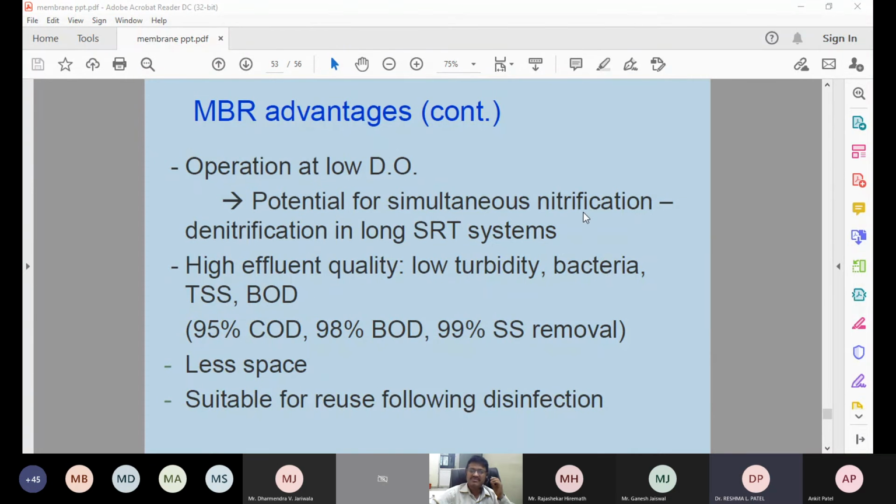Sir, for potable water supply, the recommended TDS value is 500 or less. If an alternate source is not available, then it is relaxed up to 1500. In the earlier code, it was up to 1500. My point is that in groundwater resources the TDS is always higher. Minimum it is 700 to 800, even for alluvium sources. Why are RO systems recommended, sir? I simply cannot understand the reason.